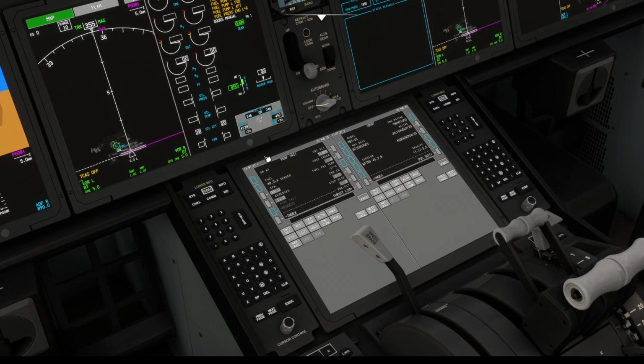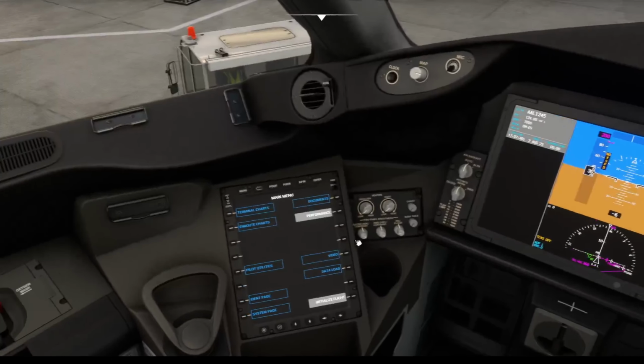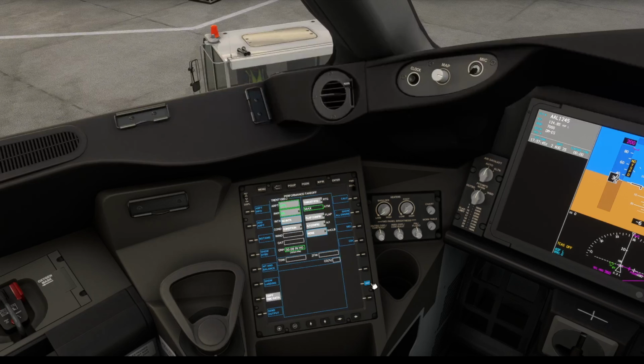And basically now we would in real life wait for the load figures, load sheet, and you're gonna leave the performance page blank for now. So now I would continue with the further setup of the cockpit. We can actually initialize the flight and put this on for our performance calculations later. This is pretty close to what we use in our airplane. We got this on an iPad, the performance program, to get the speeds and landing and takeoff distance. And yeah, it's pretty nice.